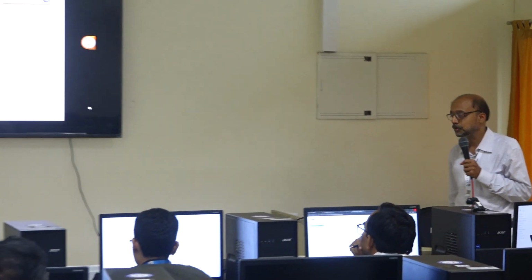So coming to radiation participating media, this is your RTE, which you are already aware of. I have given the total RTE including the transient part. The transient part is sometimes applicable for ultra short time scale applications. Here you can see this has significance in ultra short time scale phenomena, because you see the denominator term, that is the term c, which is the speed of photon travel, which is the light speed.